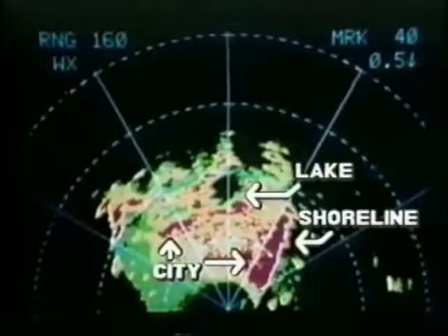The display will provide a map view of prominent landmarks such as cities, lakes, rivers, shorelines, and other terrain features that lie within the beam of the radar. Because the intensity of ground returns varies widely based on the angle the radar's beam is illuminating the ground, the manual gain control may be useful in obtaining an interpretable ground map display. You should generally fine-tune a map display by varying both the gain control and the antenna tilt angle settings until the presentation is satisfactory. Whenever possible, it's good practice to sharpen your mapping skills on known ground targets in good visibility.